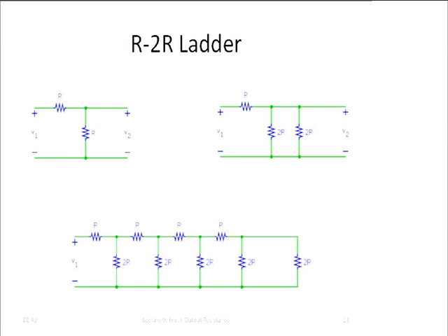What I want to do here is build a circuit that takes some input voltage, let's say 4 volts, and then produces voltages half that, 2 volts, again half that, 1 volt, half a volt, quarter volt, and so on. You may ask yourselves, why is this important? Well, it turns out that's a circuit that's terribly often used in analog to digital converters and digital to analog converters. So basically, those things that connect real devices to a computer.